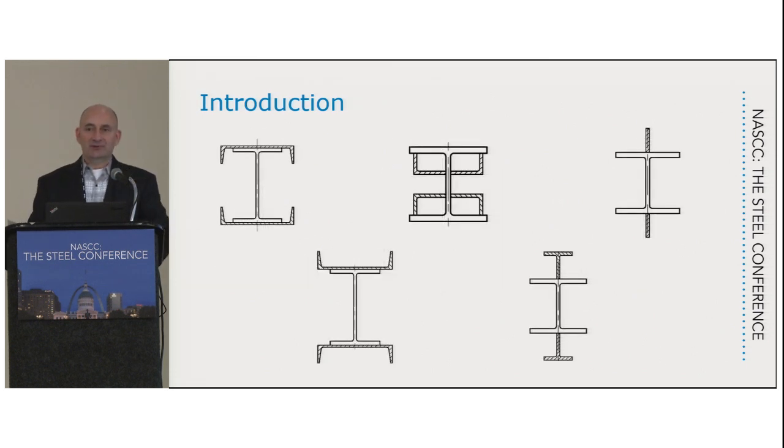And then with this slide, I kind of just wanted to throw a lot of things up there just to let you know we're not limited to just the ones that I've shown you. You can do whatever you want. It's up to you to use your judgment to come up with a way to reinforce this column and the best way that gives you the right strength and stiffness, and also satisfies the owner's requirements.